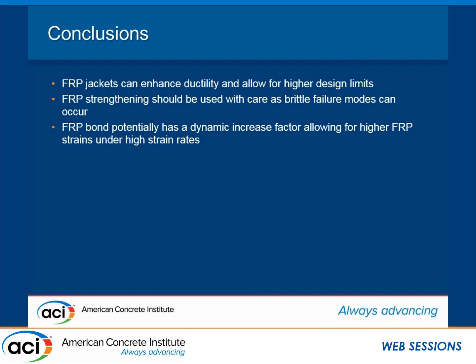What is the equivalent TNT that you're using in your test? Well, off the top of my head, I don't have that one for these ones. I'm sorry, but it's tremendously variable. And then there's the question that the load transfer device that we had was about 13 times wider than the column. So the equivalent TNT depends on how you factor that in, because there's a tremendous amplification of both pressure and impulse with that. But what I can say is it's high TNT values, very far away. So standoff distances are quite big.